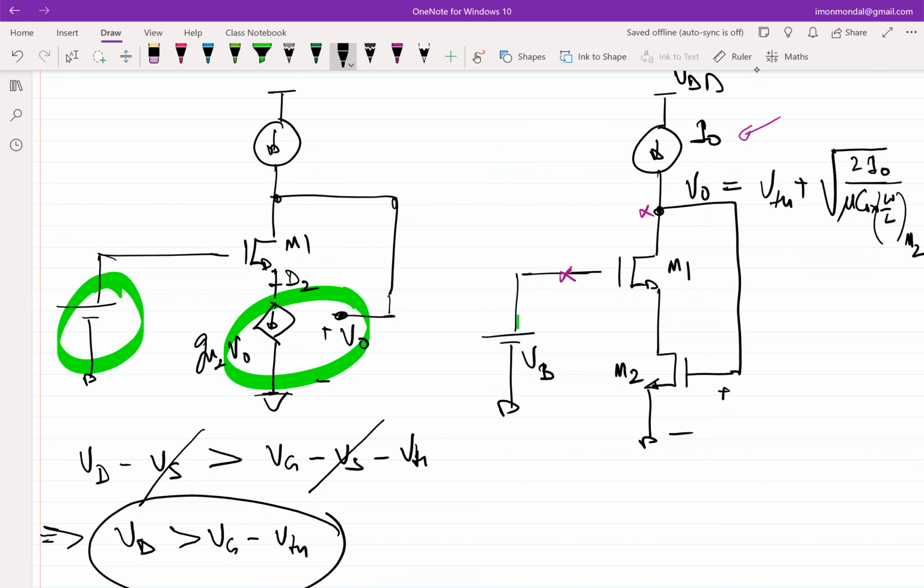So similarly here, if you don't know anything in a design, you say, okay, I will start off with M1 and M2 to be equally sized. If it's required later on, if I figure that that is not good enough, I will change it. But you can start off with equal size. So let's assume that they're of equal size.